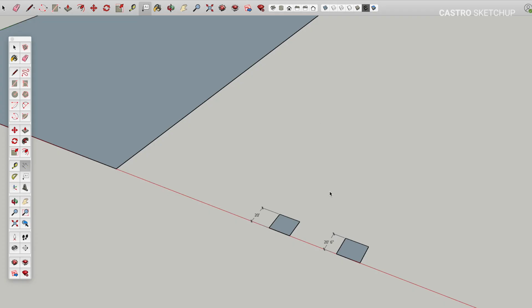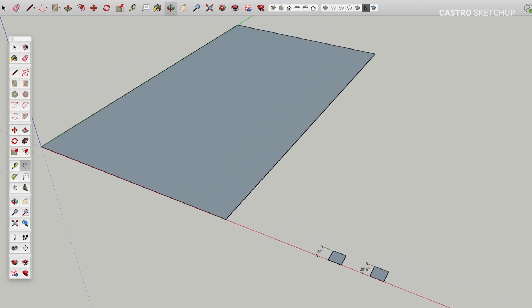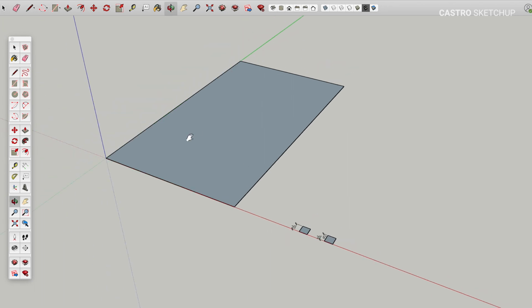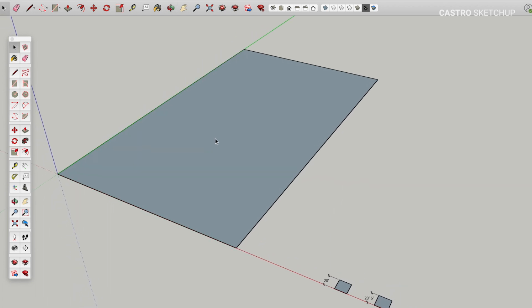Okay, so now that we've drawn these surfaces, let's talk about how to actually select them. In the tool palette, you will see this black mouse icon here, and the shortcut for that is V on your keyboard. What the V command does is essentially turn your cursor into a black pointer. I can click once, and this selects the surface itself. If I click twice, it's not only selecting the surface, but also the lines.